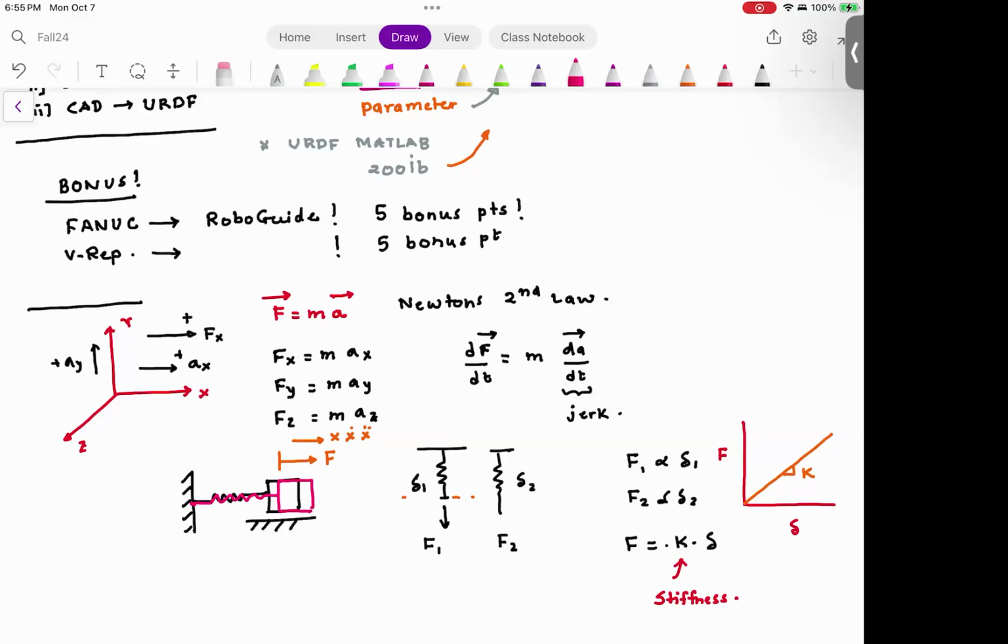And what would happen is the spring would exert a force equal to the stiffness of the spring multiplied by the displacement of the spring. The mass is displaced right by x amount, which means the spring is stretched by x amount, which means the spring would be pulling the mass back by stiffness multiplied by the displacement. Force is given in newtons, stiffness is given in newton per meter, multiplied by meter. So I have the force on the right, force on the left.